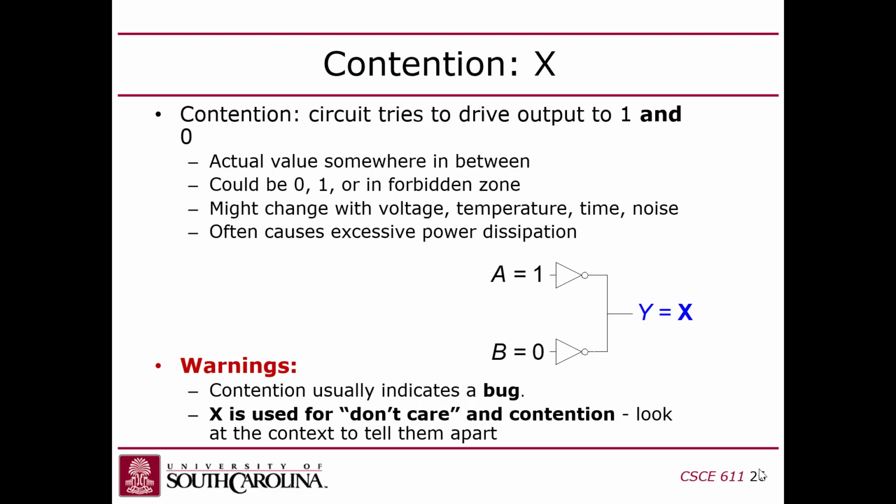Now, remember, I don't know if I had this in an earlier slide, but every net, a net being like a node, think of it like in Spice, you have a node. Every wire, every variable can only be driven by one driver, one gate, right? So you have to be careful when you write Verilog, and I'll get into more detail about this, but keep in mind that you cannot have more than one circuit connected to the same wire for its output.